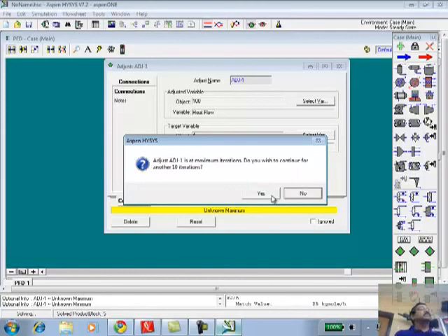Or what else can you do? You find out where I can specify to increase the number of iterations. So you should understand these concepts of what iterations are and what the maximum number of iterations is, so that you have the path forward to jump across this hurdle. We have specified the problem, and it's not really bad, we figured it out in 5 minutes, right? How to set up the adjust block. It's basically identifying the target variable, the adjusted variable, and specifying the target value.